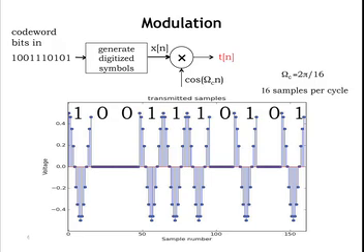What I'm not showing you is the D2A converter, which is going to take this thing and interpolate these points and put it out on a real-time axis and put it out on the channel. Okay, I'm imagining all of this going on, but we're just going to look from discrete signal to discrete signal. So I'm suppressing all the stuff in between.